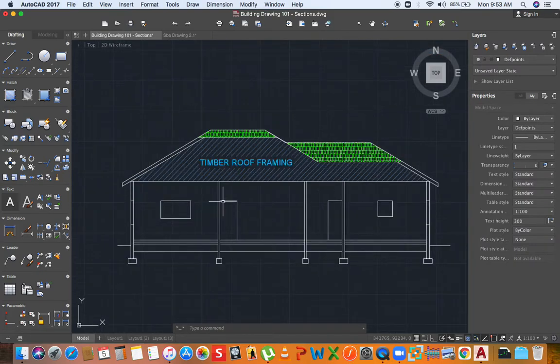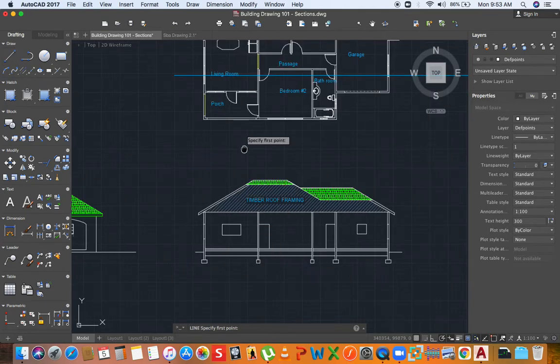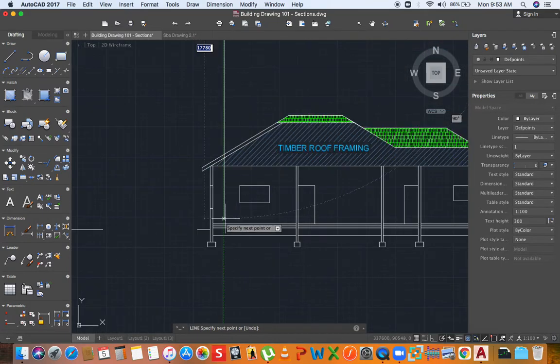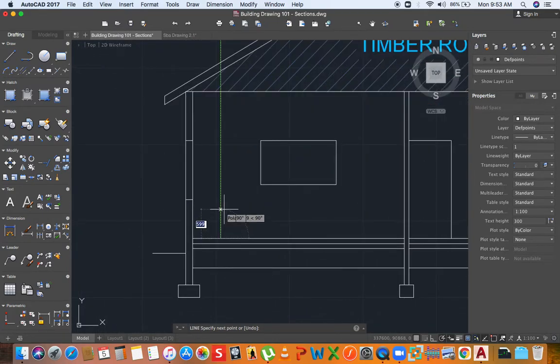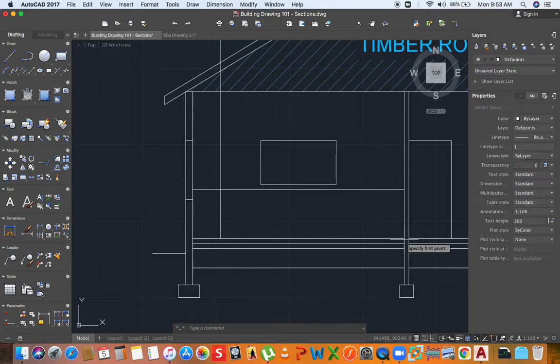Doesn't matter. Now all you're going to do is to draw in the fixtures. The counter now would be 1,000 millimeters high. So this is the height of the counter, and it goes all the way to the next side, and this is also 600. So if you realize this count, if the window was lower, it would go below the counter, and that's not what you want. Alright, so this is the 600 from the wall to this side, 600 from the wall to this side.